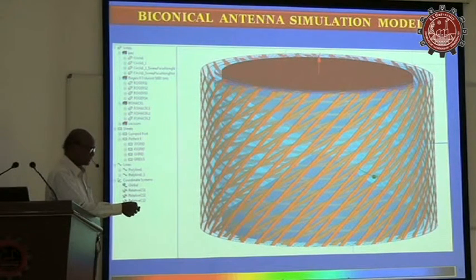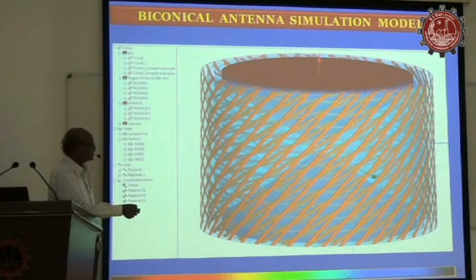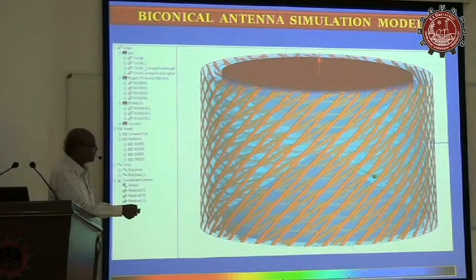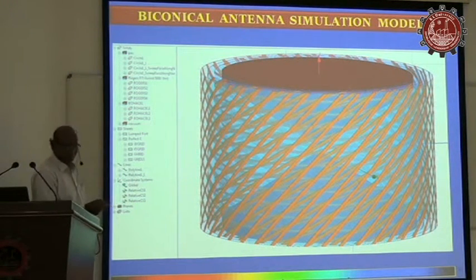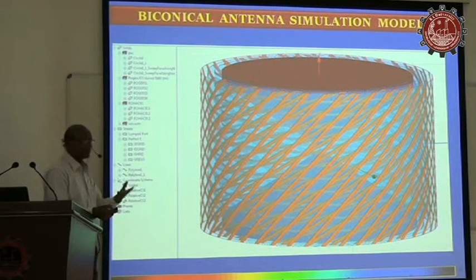Whereas using this simulation software, we have modeled these grids using HFSS, and there are various parameters in this. You can see one parameter is the grid width, the spacing between the grids, then the spacing from layer to layer. All these are parameters. One beauty of HFSS is it has Optimetrics, parametric analysis.